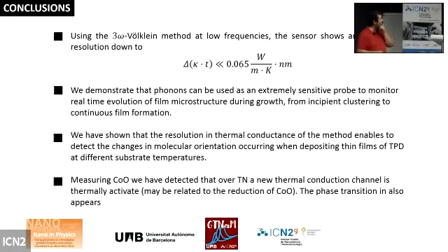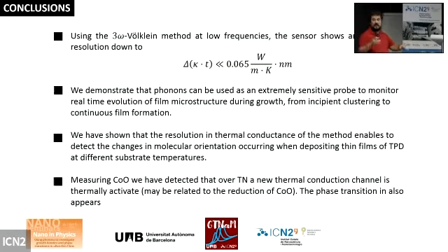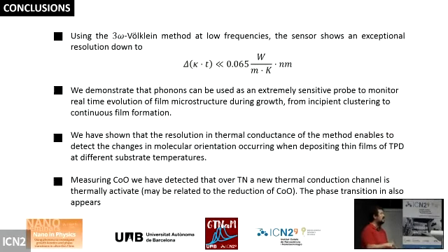And I wanted to summarize. I hope I've not been too short, but I wanted to summarize the talk, saying that using the 3 omega Völklein method at low frequency, the sensor shows an exceptional resolution. As soon as we are measuring thermal conductance, we have to introduce the thickness in order to give the resolution. The combined resolution is below 0.065 watts per meter Kelvin per nanometer.